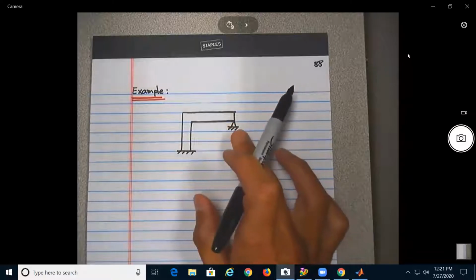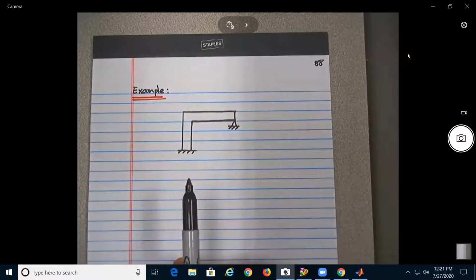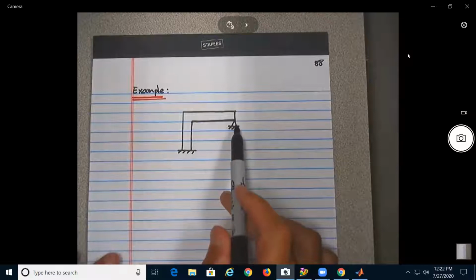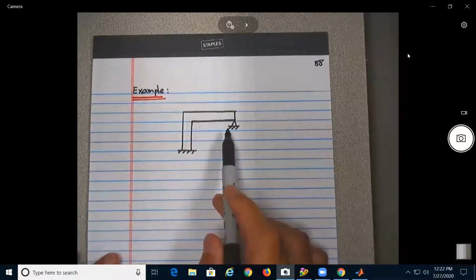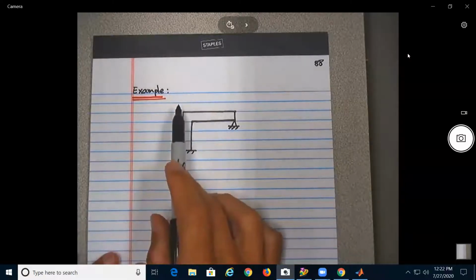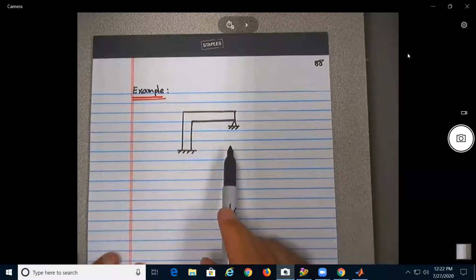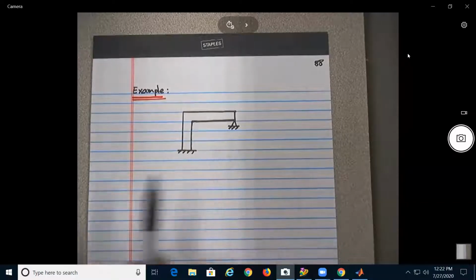So it's just redundant. So this problem means that this one's going to have more unknowns than equations, than the three equations we can use from statics. Okay? So this is called a problem which is statically indeterminate, no? Meaning that we need to add the additional equation.